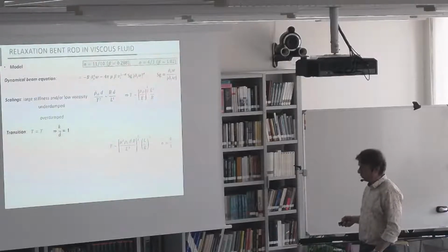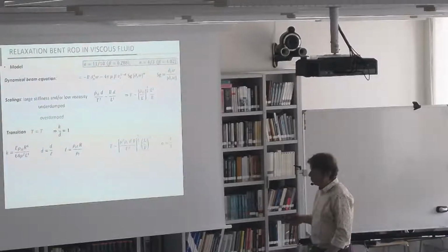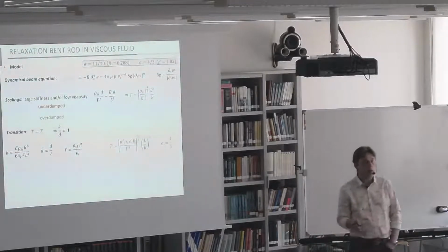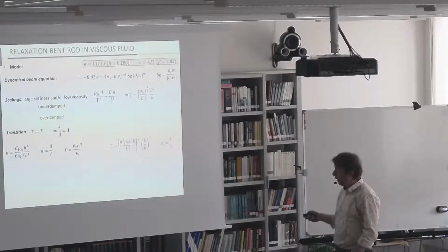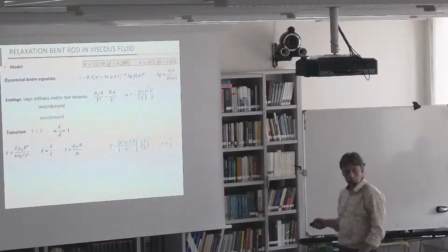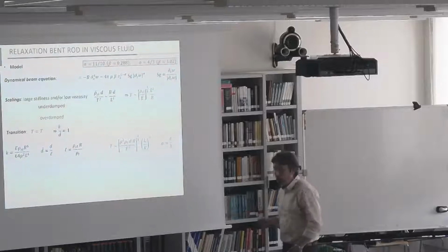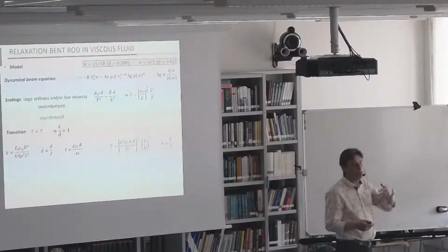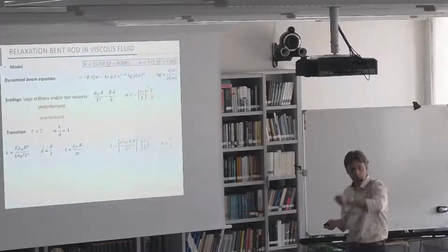And what are those dimensionless parameters? You have k here, which involves essentially all the parameters of the system except the initial displacement. And d bar is d over L, where L is essentially the radius of the rod. And so L appears as a suitable length scale to rescale the transverse motion, because d is the initial displacement in the transverse direction.